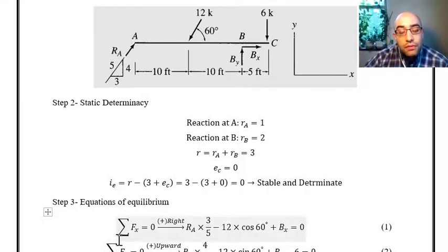This is the equation, summation of forces in x direction is equal to 0. So positive is in the right direction. The x component or horizontal component of this reaction will act in the x direction, to the right. So that is positive, and the value is Ra multiplied by 3/5, the horizontal side over the side that represents the direction of the force. So Ra multiplied by 3/5, that is the horizontal component of Ra.